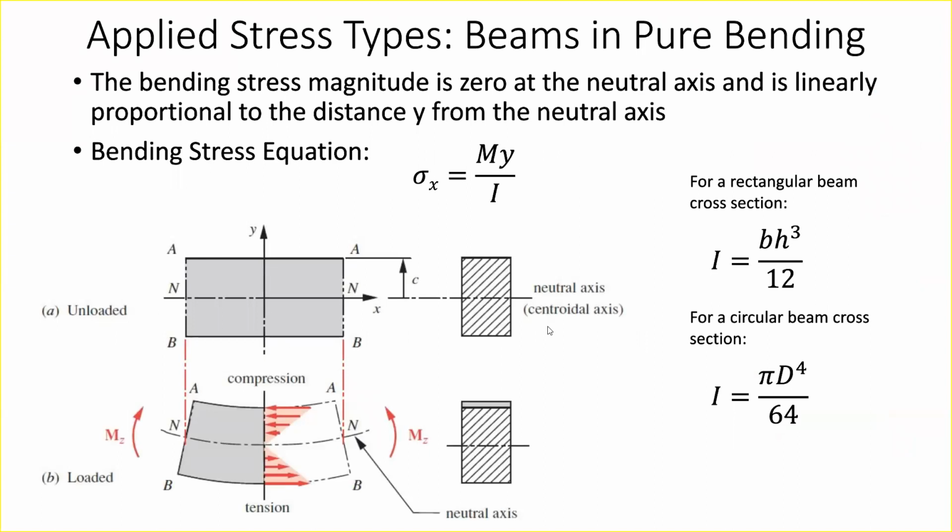Another super common type of loading that you'll see is bending loading. If I were to take my phone and try to bend it, that's a bending load. This is a really fundamental load on the car as well, and most of our critically loaded parts are actually in bending. The bending load is a fundamentally different description of how we apply force. It's actually not a force, it's a torque or a moment. The moment applies a net torque about the plane coming out of the page, so the z-axis in this case.